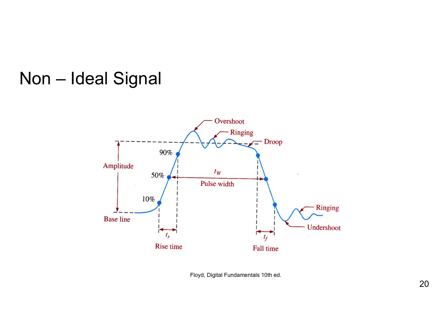Non-ideal signals. Signals in the real world are not nice and perfectly square. They're more distorted, and they can be distorted because of overshoot, where the signal goes above its baseline amplitude. Ringing, droop is where it falls a little bit below.